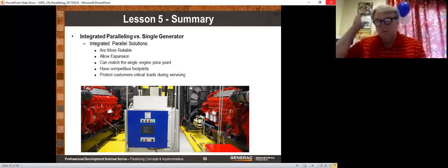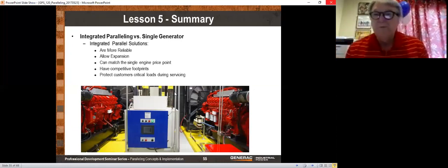That causes the power to go down and eventually will ruin the engine. That is not a problem with parallel generators. It's a problem with diesel generators, and it doesn't matter whether they're paralleled or not. So we generally recommend that once a year, sometimes once every 2 years, you bring in a portable load bank and you run those generators at full load. Wet stacking is caused by carbon deposits, and so we load bank them, we get all those carbon deposits burned out, and we can restore that engine to like new condition.